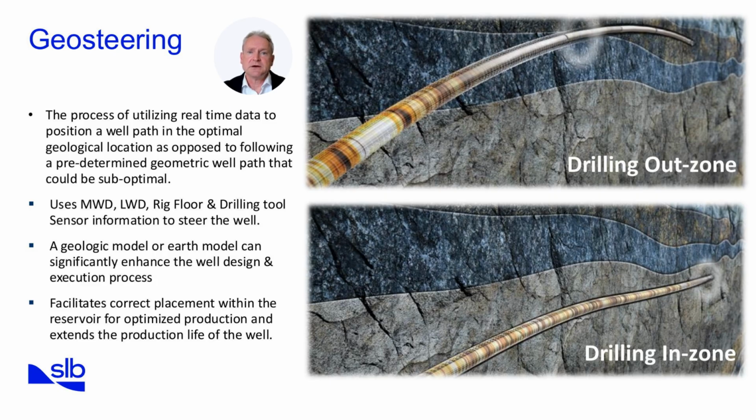The benefits of geosteering are that it maximizes reservoir contact while reducing drilling risk. It enables proper placement, increasing the productive life of a well. It also improves field development, where each geosteered well feeds data back into the reservoir model, improving the design of future wells. Finally, it helps optimize well spacing, target selection, and completion strategies.